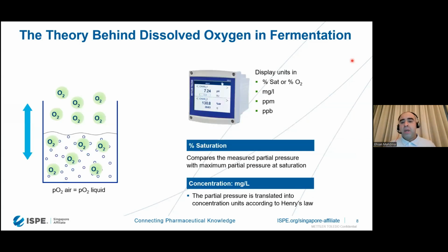And so then it becomes a matter of measuring the solubility of oxygen, or let's say the presence of solubilized dissolved oxygen, or DO, in the aqueous form. So we have two strategies at hand. On one strategy, we can go ahead and estimate the precise or absolute concentration of oxygen dissolved in the aqueous form. And for that, we need to bring in all the parameters that affect solubility: partial pressure of oxygen in the gas form, relative humidity, barometric pressure, gauge pressure, salinity, chlorinity, and therefore, through an empirical equation, come up with the milligram per liter, ppm or ppb, depending on the range, of solubilized oxygen in the water. We can calculate and report that